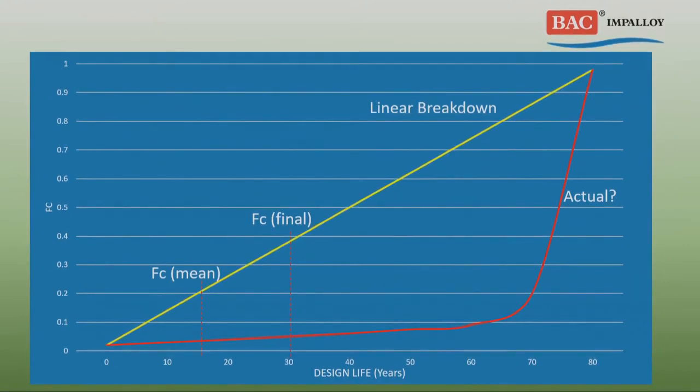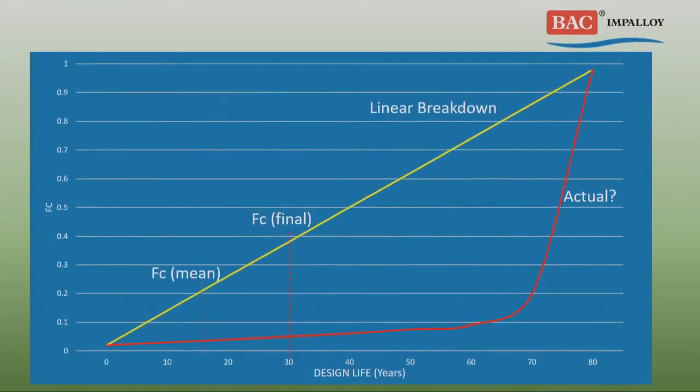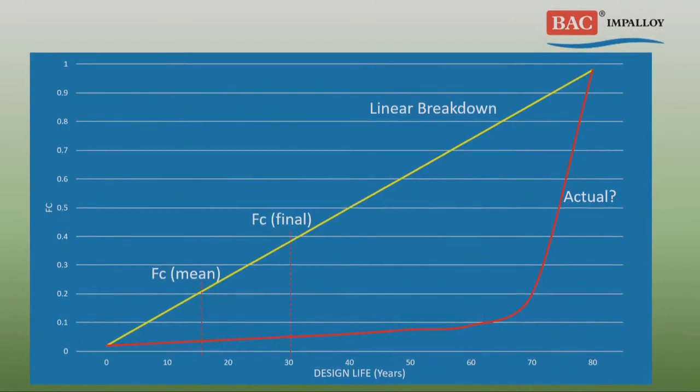Well, the actual model might be, we don't start at 0%, by the way, because we recognise there is some coating damage before the coated structure hits the water. There will be a gradual increase over the years in the coating breakdown factor and therefore the amount of current, because you get blistering, you get inadequate cross-linking and all that kind of thing, and some mechanical damage to the coating. But once the conductive path starts hitting the substrate, then you'll get a dramatic increase.